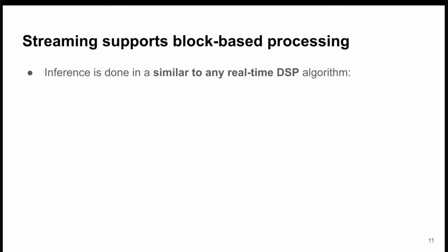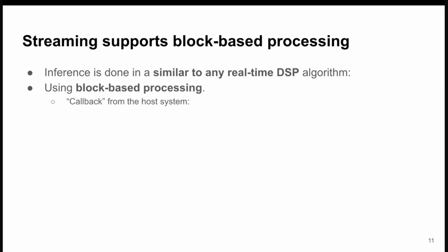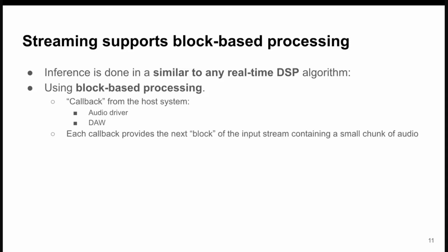For the specific case that we're talking about here, that's mostly what we're going to want to do. In order to do this streaming implementation, we're going to do it a little bit similar to how we would do most other real-time DSP algorithms. So we're going to have a block-based processing framework. Usually the way this works is that you have some host system, maybe it's your audio driver, or if you're in an audio plugin, the callback is coming from your DAW. The host system will give you your data in chunks, and it'll call some function that gives you new data, and you're supposed to give it back the processed data.